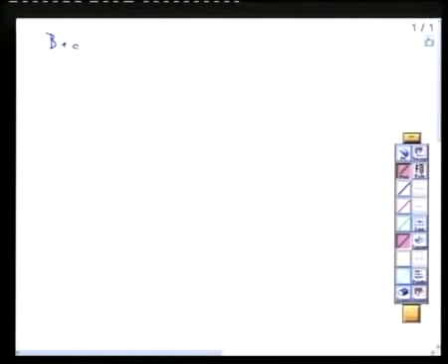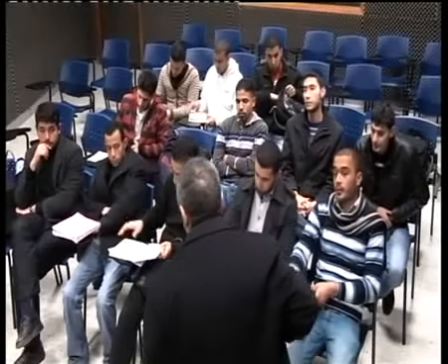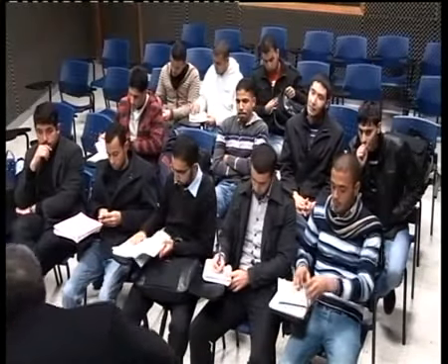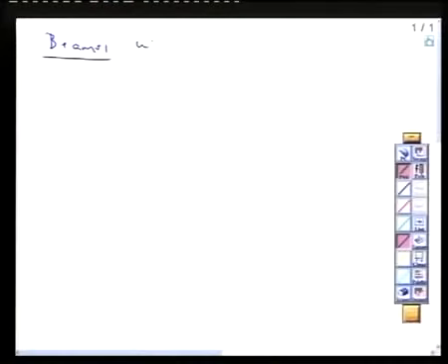Beams. Beams fail either in local buckling or lateral torsional buckling. For local buckling, we divided the section into three: compact, non-compact, and slender. In beams, we like the sections to be compact. Use compact sections. Otherwise, you have to calculate the capacity in the same way that we are going to learn how to calculate its capacity under lateral torsional buckling. So here is local.